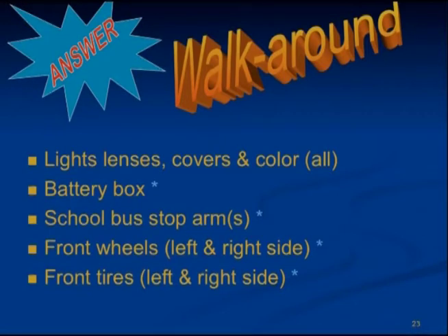And note, it is easier to check the steering system, front suspension systems, and front brake systems with the hood open while checking the engine compartment. You may choose to do differently.